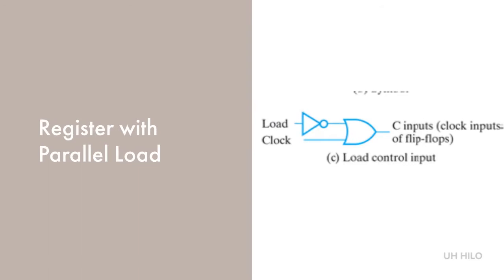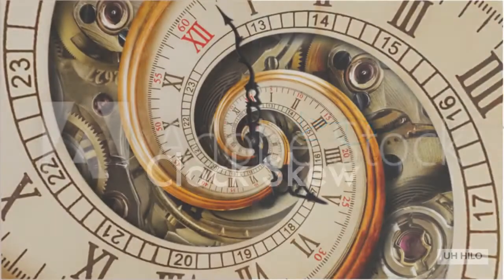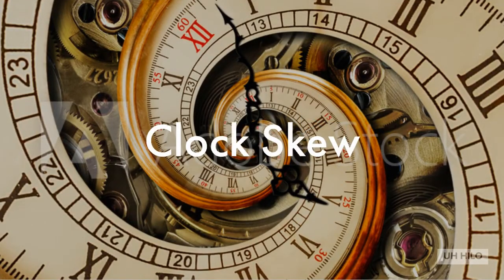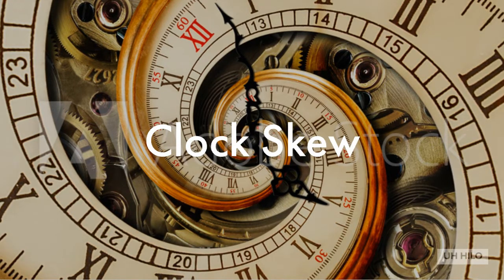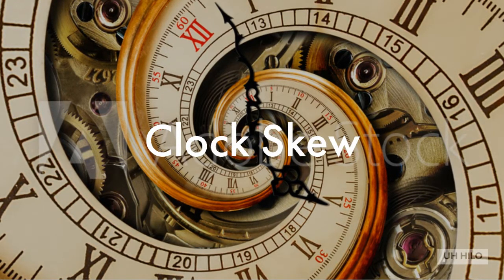If we want to leave things unchanged, we can prevent the clock from reaching the clock input. To do this, we use a separate control signal to control the clock cycles during which clock pulses are to have an effect on the register. This approach can be implemented with a load control input combined with the clock. Inserting gates in the clock pulse path produces different propagation delays between the clock and the inputs of the flip-flops with and without clock gating.